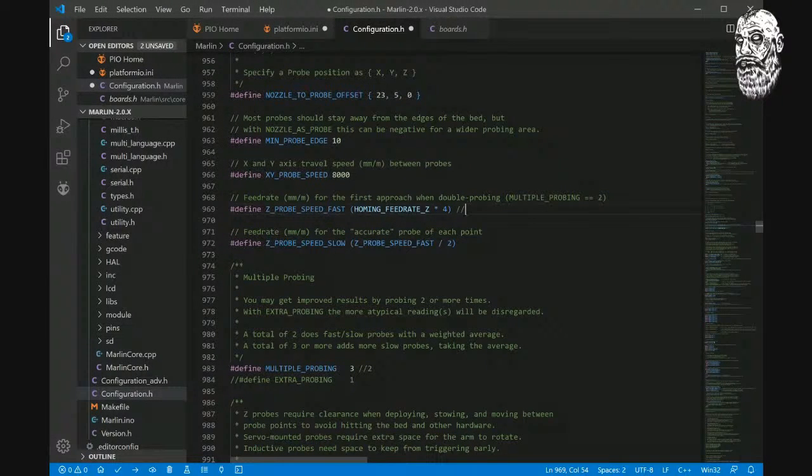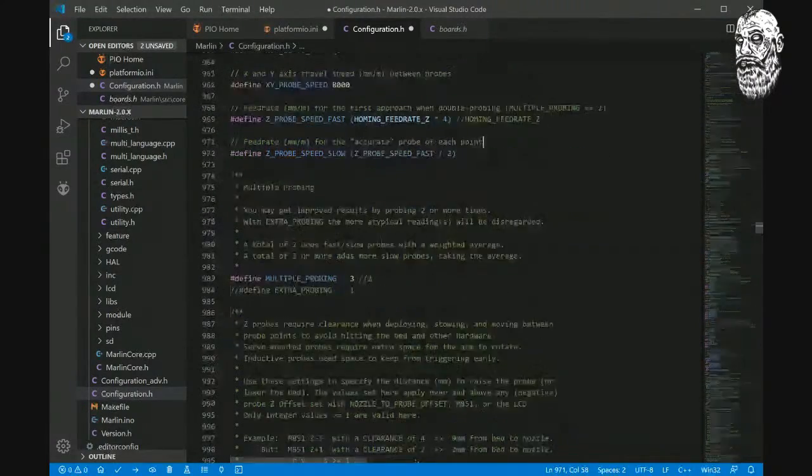again, I started slipping here. This is what it normally is. Okay. It is also for homing XY. So if you do, no, that's not for homing. This is just your XY probe speed. So when you're probing, this is different. This is faster than our homing speed. Homing is very slow.